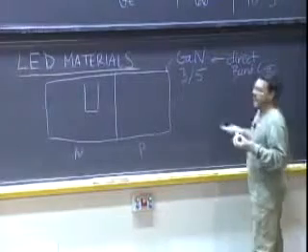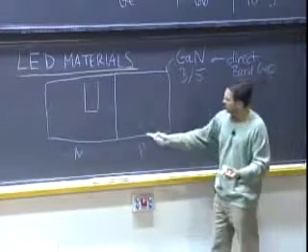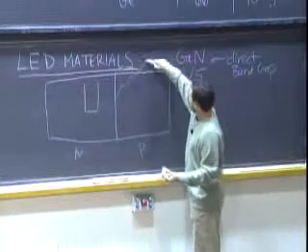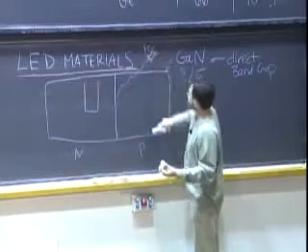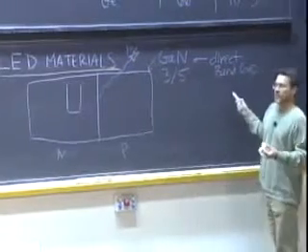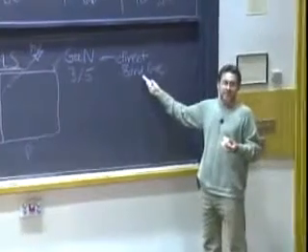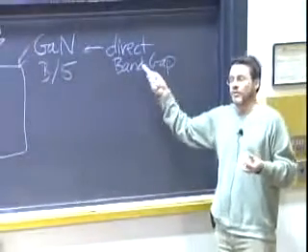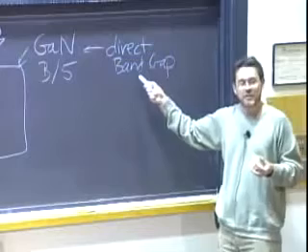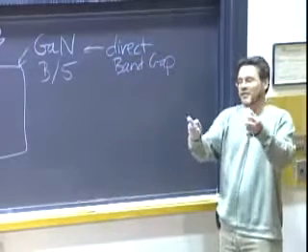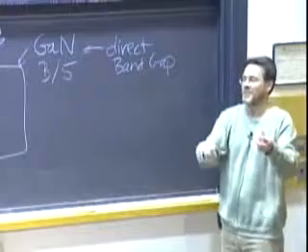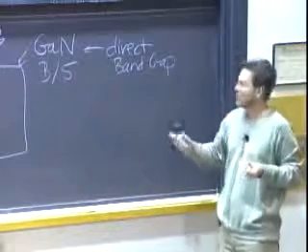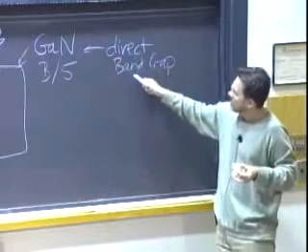And as direct band gap materials, when the process that we're going to talk about here takes place at the interface, then out of this interface comes the light. Okay? And if your semiconductor material is an indirect band gap material like silicon is, then that is not the case. That has to do with the solid state physics of electronically, where is the conduction band located relative to that valence band? Is it shifted horizontally in solid physics speak relative to the valence band? That's what makes a semiconductor an indirect band gap material.